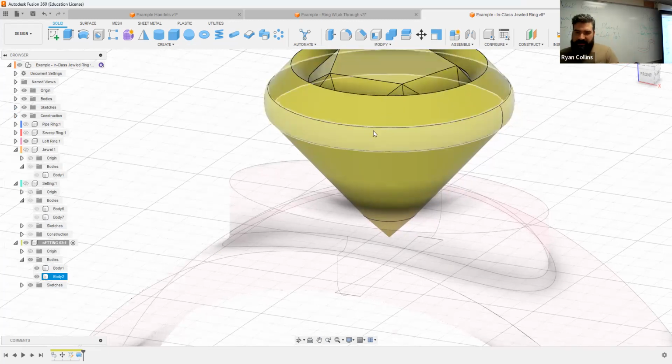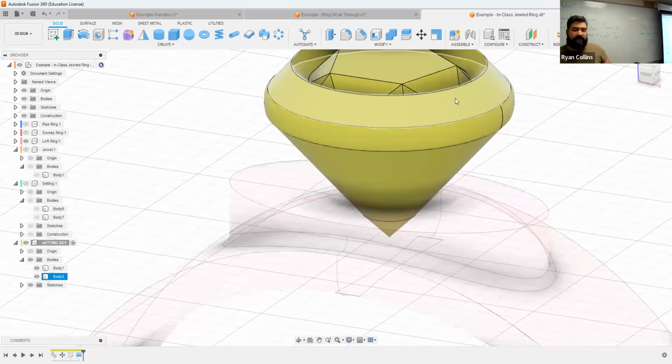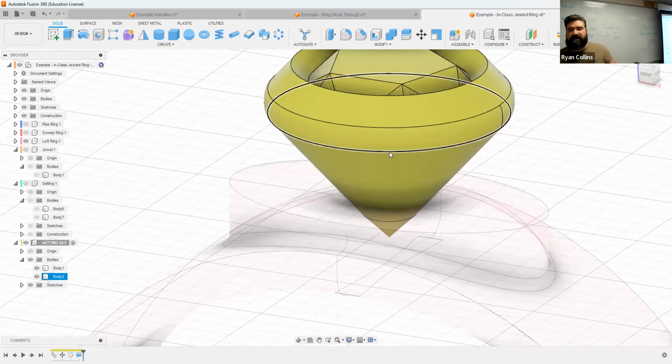Okay, so the reason I built it like this is because I'm going to use extruded sketches to chop chunks away and reveal the setting that way. Like when we experimented with making the revolve planting vessel, and we projected shapes outwards to create holes in the sides. Same deal here.